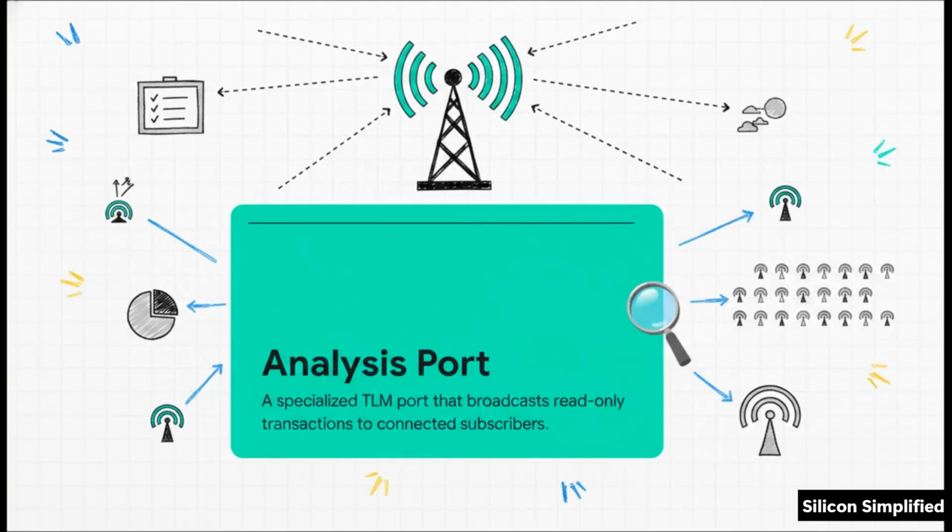Enter the analysis port. This is a specialized TLM port that operates exactly like a radio tower. It broadcasts read-only transactions to 0, 1, or even 20 connected subscribers simultaneously, all using a single write function. These are absolutely perfect for passive components, think scoreboards or coverage collectors. The component broadcasting the data doesn't block or wait. It just shouts the data into the void, and whoever happens to be tuned in gets a copy.